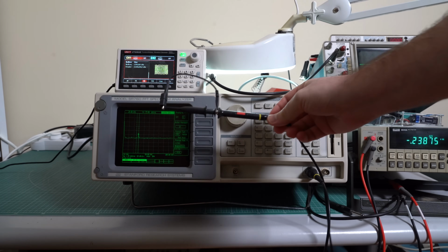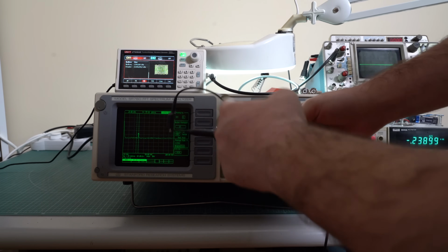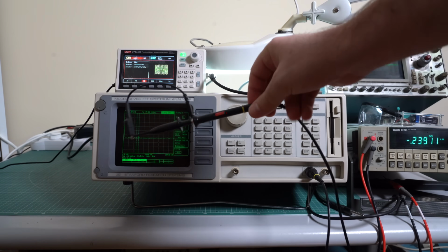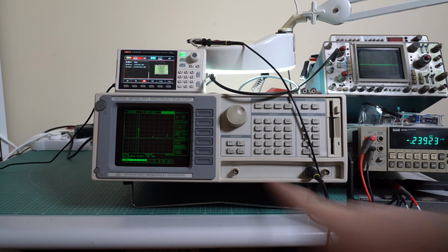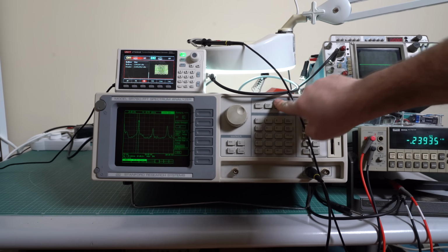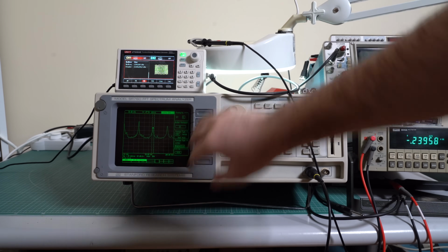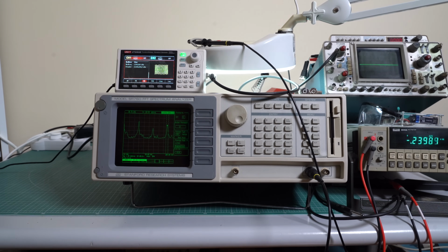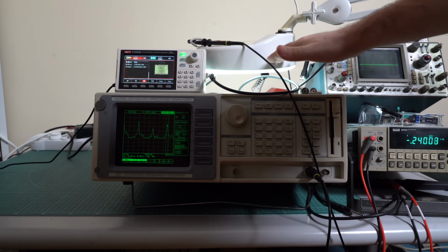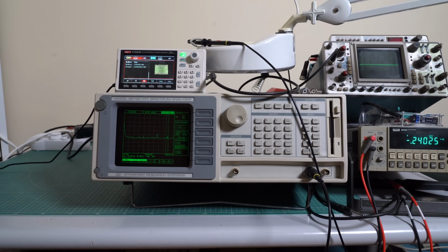All I have here is a scope probe that's shorted out and is connected to the spectrum analyzer, and this loop of wire acts like an antenna. Watch what happens when I put it close to my desk lamp. As you can see, we have some spectral components here at around 30 kHz, 60 kHz, so this is the second harmonic, and also at 90 kHz. So this means that this desk lamp puts out some radio frequency noise. And we know it comes from the desk lamp because we can turn it off and the signal is gone.